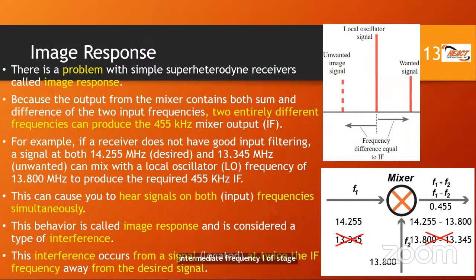So there's a problem when we use superhet or superheterodyne receivers and the concept of heterodyning or mixing. You probably sensed it already from what we discussed. We actually get two outputs. One is not useful to us, or we are not interested in one. That's the problem right there. Because of that, we can also generate another signal, a ghost if you want to call it that, an image of the one that we're interested in. And that one actually happens to be twice the IF frequency away from the one that we're interested in. So that is actually an exam question.